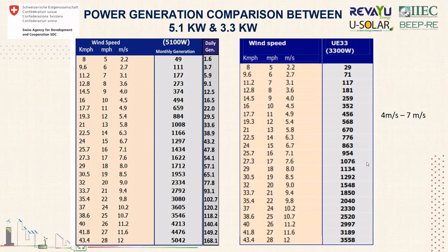In this case, as the wind speed increases, instead of the thumb rule of 4 units, we have been able to generate with the 5 kilowatt model itself, at 8 to 10 meter per second wind speed, around 60 to 70 units from a 5 kilowatt turbine on a single day, which is approximately double the capacity expected from a normal solar installation.